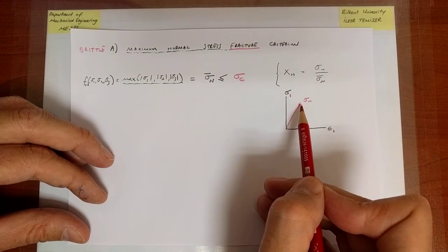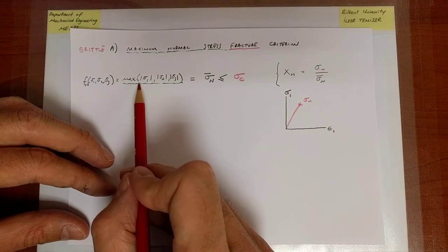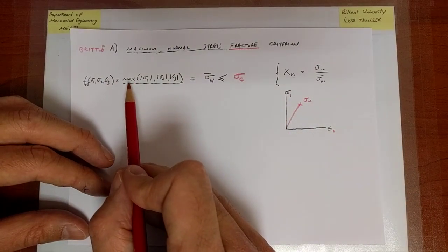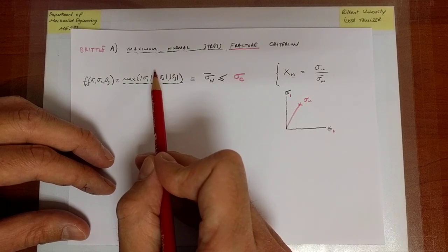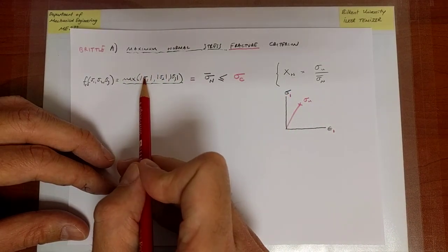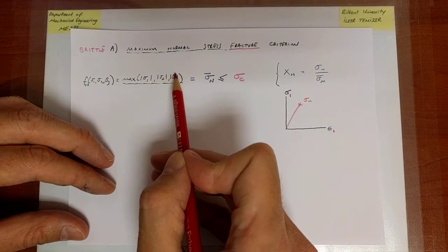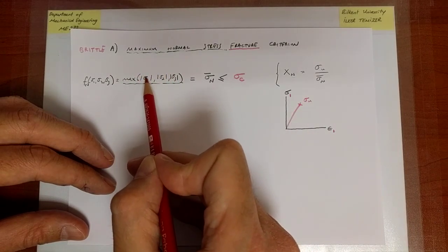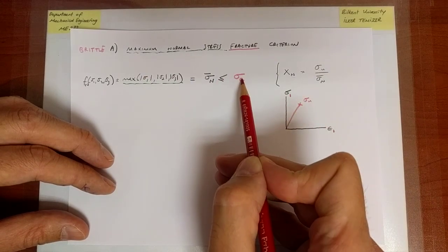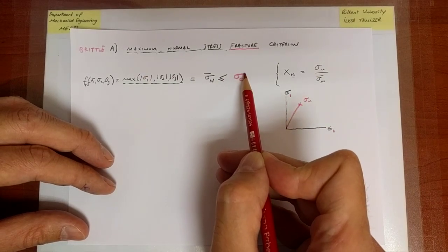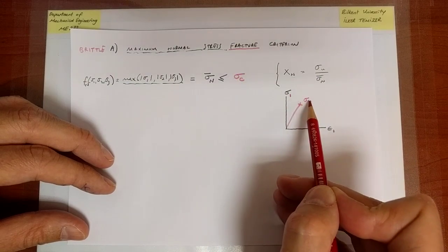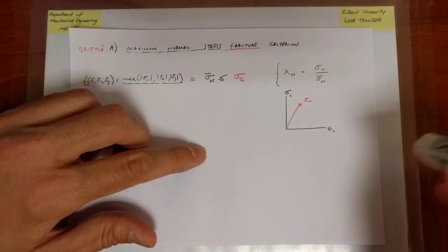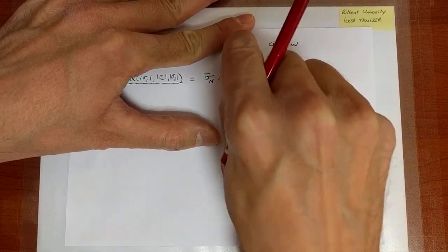If it doesn't work for the simplest possible scenario, it possibly cannot work for a more complicated scenario where there are multiple stresses present. So I take the scenario, put it in there, and in that scenario, sigma 2 is 0, sigma 3 is 0, there is only sigma 1, and therefore its absolute maximum value cannot exceed the ultimate strength, and that's how I know that the critical value is equal to the ultimate strength of the material. And that's why I've written it directly.